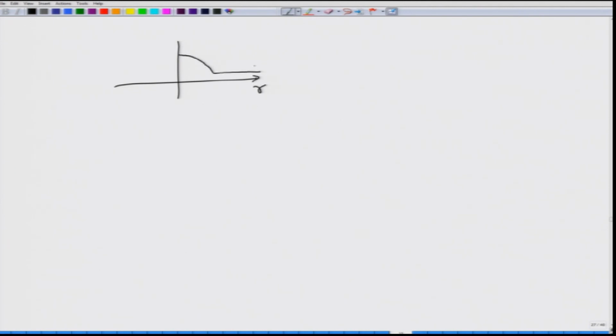In this graded index fiber, the refractive index of the cladding remains constant at N2, whereas at the center of the core the refractive index is N1, but the N1 to N2 transition does not happen like a step, okay, but actually happens more like a graded profile. Okay. How is this bending? This bending curve is characterized by the profile parameter called alpha.